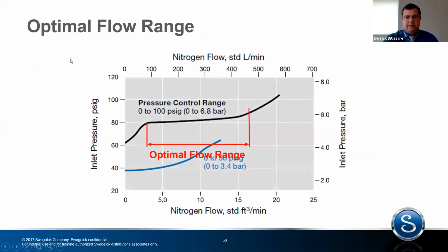And I guess what I didn't talk about before, with a flow curve, if you have a range in here and it's not exactly where you want it to go, let's say you don't want this at 80 psi, you really want to know what it is at 70 psi. For most regulators, you're able to drop a flow curve down. You don't want to move them up because it may go outside of the regulator capabilities. You can take this curve and move it down to get a representative performance curve out of them, whether that's a back pressure regulator or pressure reducing regulator. If you see a published flow curve, you can move it down. Don't shift it left or right, but you can move the curve down to get a representative performance out of that regulator. Should have brought that up before.